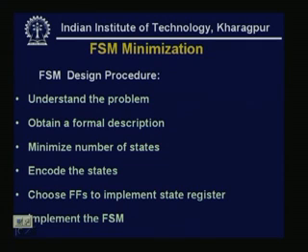Now if we see the full FSM design procedure, what will we be doing? First we should understand the problem, then make a formal description, then minimize the number of states, because ultimately our aim is to make an efficient design.